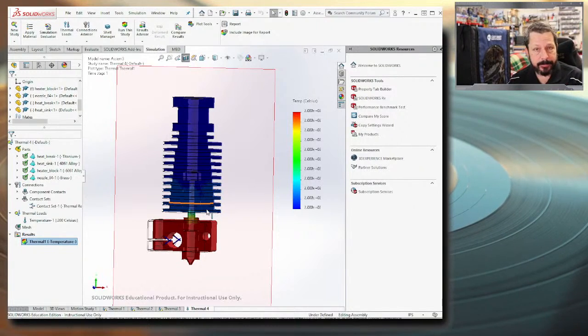So that would eventually happen. But it doesn't even have to get to 200. As soon as you get to, depending on the material, 70 degrees Celsius, maybe 80 degrees Celsius for some materials in this zone, then it has softened the filament to the point that it is not able to be pushed out of the nozzle. So it doesn't have to get anywhere near this bad.